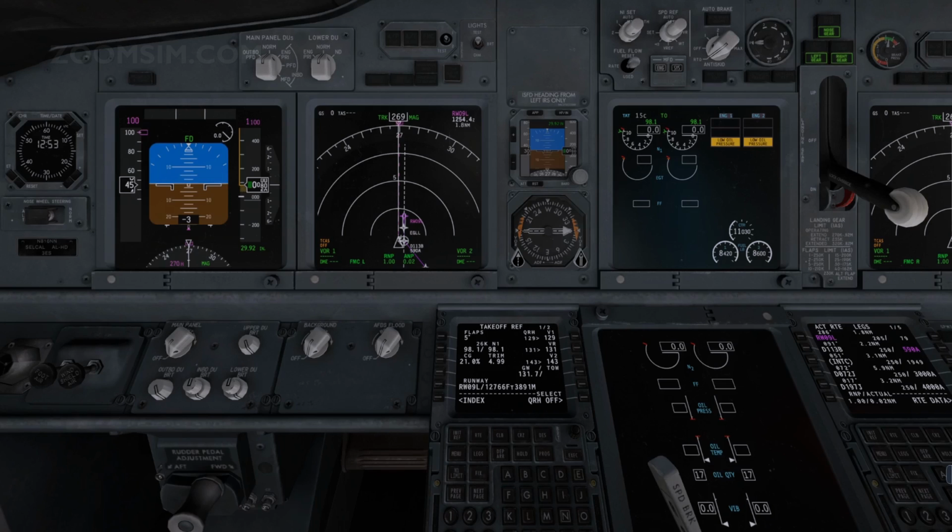Fuel flow, rate. The fuel flow switch has 3 positions: rate, used, and reset. The rate position displays fuel flow to the engine. In the used position, pointer and shading are removed, and fuel used since the last reset is displayed. After 10 seconds, the display automatically reverts to fuel flow.